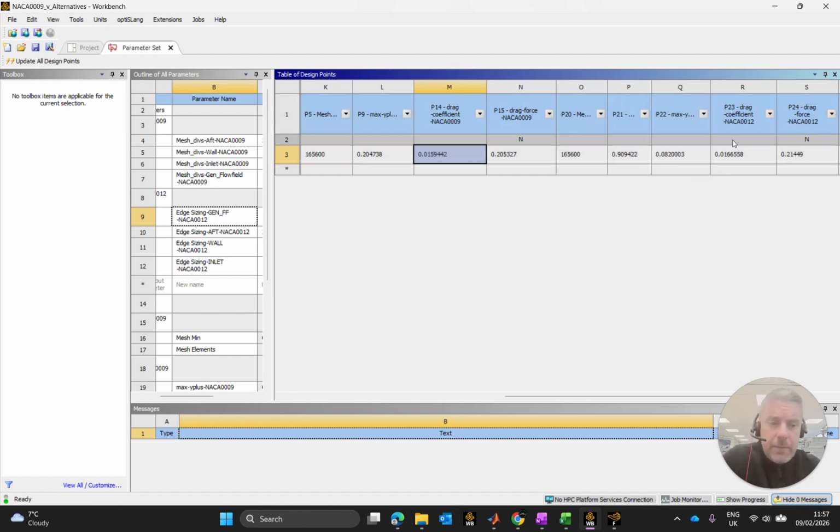But probably what is happening here is going to be these other parasitic losses, the likes of the laminar separation bubbles that are forming on the NACA 0012 airfoil, could be what's causing trouble on this. But there is a pretty good way to validate or get a better insight on what's going on and see is it particular to the 0012 airfoil, and that's to bring in a third airfoil, which is what I'm going to go ahead and do.